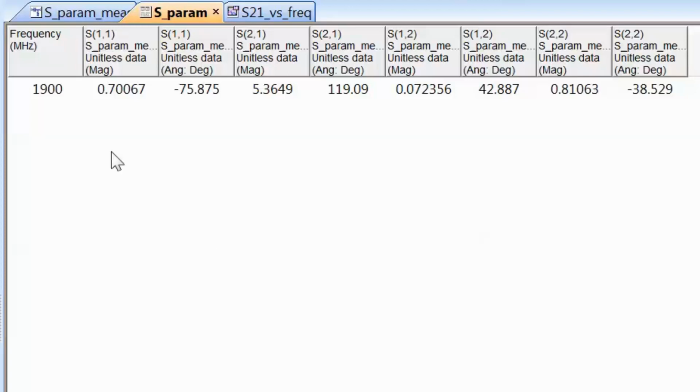So let's start with the input of the transistor. The input of the transistor will have a specific impedance which is given by our S11 here. So through S11 we can actually work out, as we've seen in other tutorials, what the actual impedance that is seen at the input terminals of the transistor is. And we've also seen that to be able to achieve maximum power transfer, what we need to connect to this input impedance of the transistor is its complex conjugate. So we basically have to transform whichever impedance we have for our source into an impedance which is the complex conjugate of the impedance seen looking into the input port of the transistor. So how do we do this?